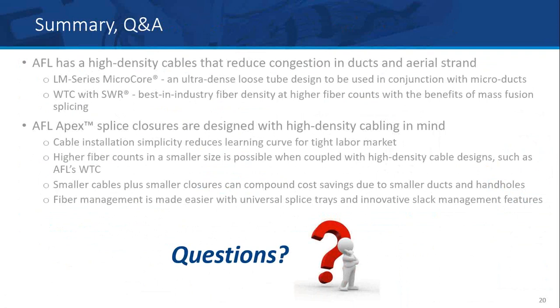But if you had to go to a 200 micron pitch, in the newest fusion splicers there is a removable fiber holder, and, what's the word I'm looking for? V-groove. Sorry. So there's a removable V-groove that does have a 200 micron pitch as well. So there is a solution out there for that. The specific how you do it, I can't remember off the top of my head, but there is. Check into some of those ribbonization tools as well as our newest fusion splicer on aflglobal.com.